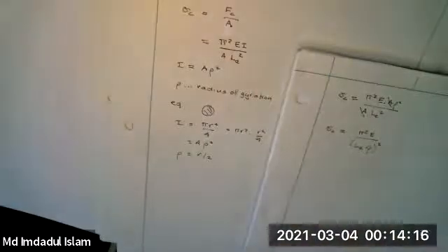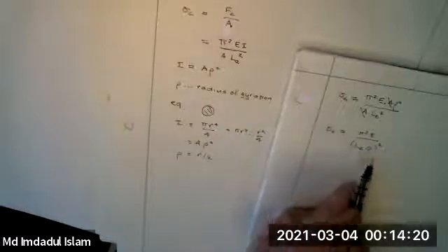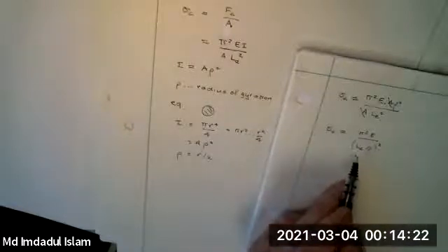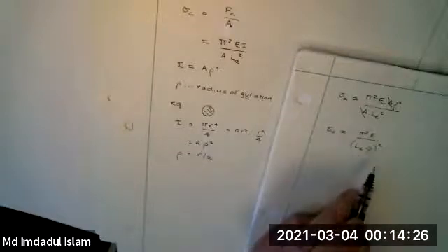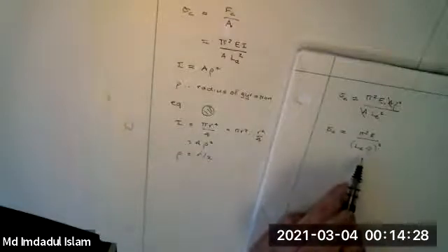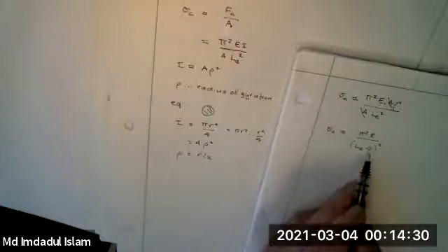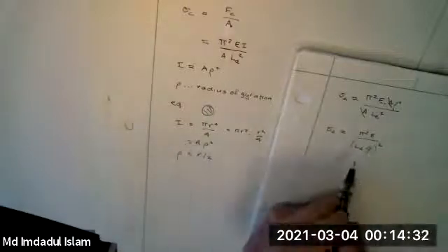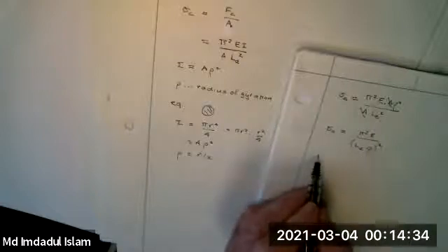So in terms of buckling, this dimensionless ratio is the equivalent length, which reflects the end conditions. Okay? Simply supported would just be the length, but then it's going to change depending on how much you restrain the end. And rho would be this radius of gyration. So this is the dimensionless ratio.